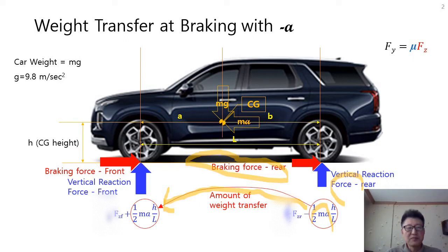Please remember, braking forces are produced differently at each wheel, relying on the individual friction coefficient multiplied by the individual vertical reaction force. Of course, we have no braking force at all if either the friction coefficient or the vertical reaction force is equal to 0.